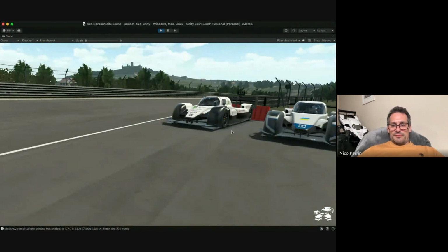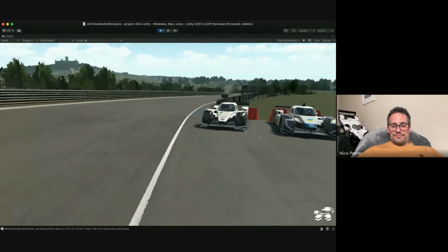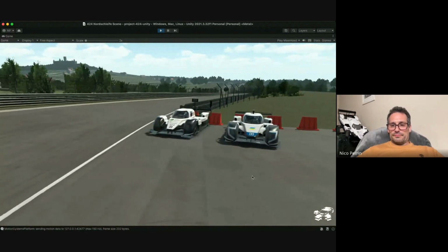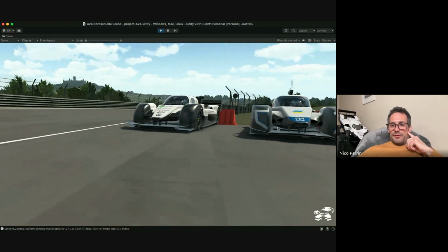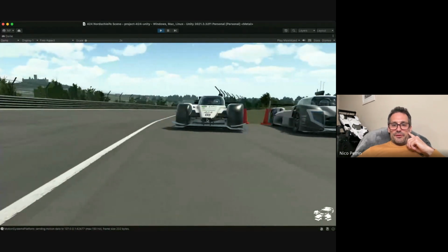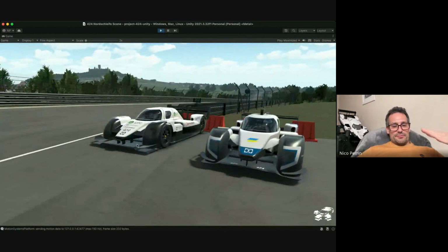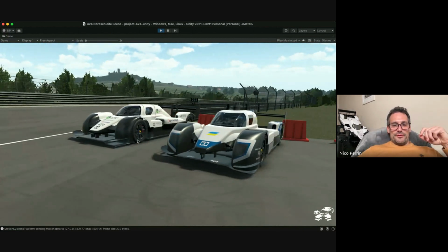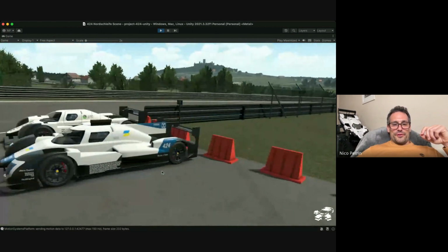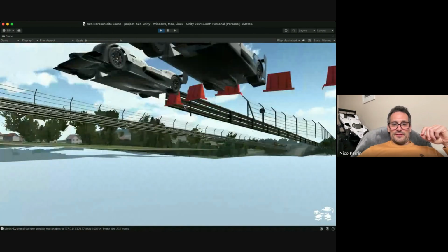I'm trying to give you a better view here. If you look at the flap, it was actually on a low angle setting. You see the flap at the back. The flap now is on the higher angle setting on the 424, but also the general curvature of the main plane in front of it is more aggressive under the car. These are changes that are a bit hard to see, but the front wing will produce about 30% more downforce in this case.